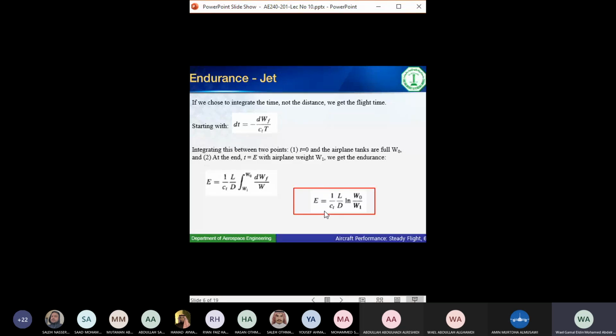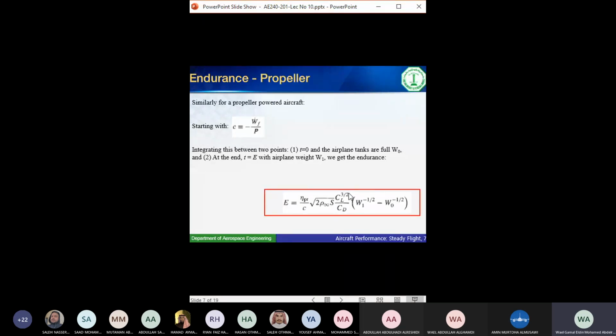And finally, the third ratio, CL to the power 3/2 divided by CD. This one is what determines the endurance of propeller aircraft. So that's why these 3 values were important. That's why there were equations for them in chapter 2. And when you asked why these are important, you solved one homework where you found the maximum of this value. I told you, wait, it will affect the performance of the aircraft. Any questions up to this point?